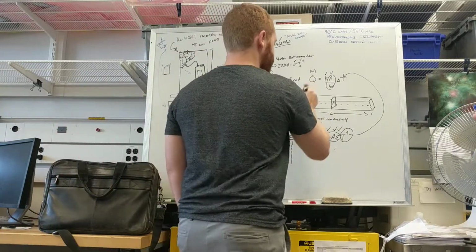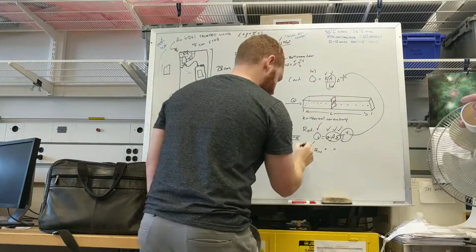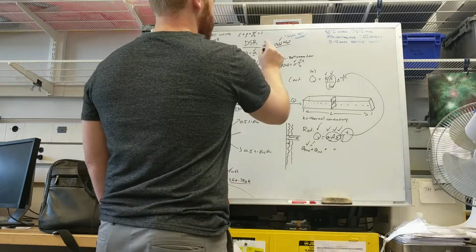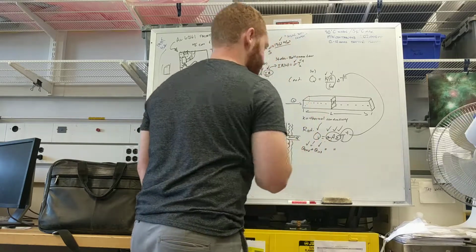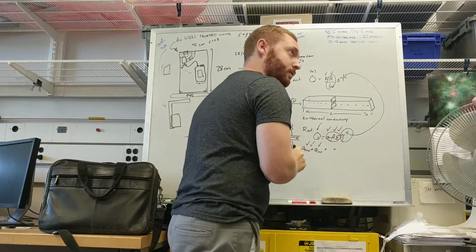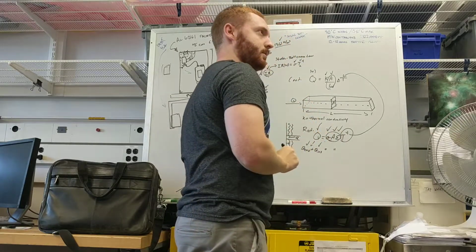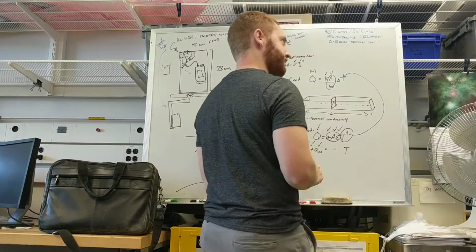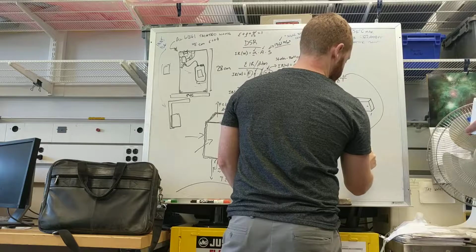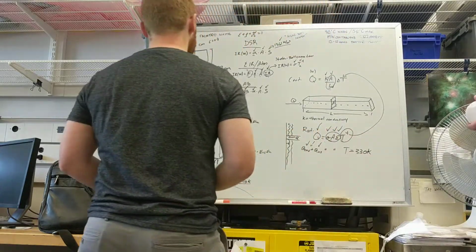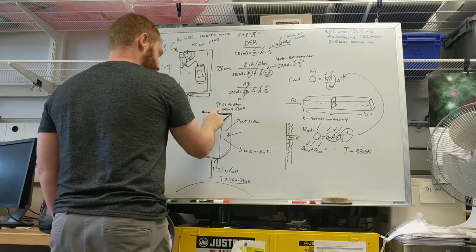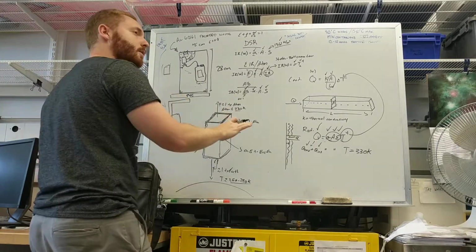So then you come to this equation and you go, okay, we know the Q environment now. And we also know that we are getting rid of 15 watts. So that Q is known. Sigma is a constant, A is known, emissivity is known. What's the only variable left? It's T. Okay, so let's say T comes out to be 330 Kelvin. Sure, 330 Kelvin. That means that no matter what you do, if you move all 15 watts, this surface will be 330 Kelvin. That's the way it goes.